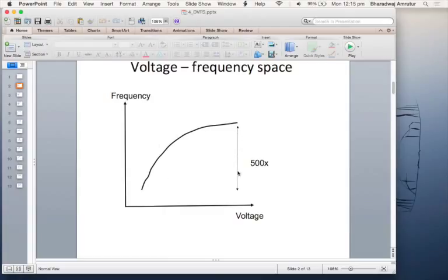But for now, let's worry about this range out here, where you drop your voltage from some max operating voltage to maybe about half of that. That is a reasonable range for your chips to run at, and you can change the voltage by about 400 to 500 millivolts, from the max voltage to the min voltage. That gives you a lot of voltage headroom to play around with to reduce your power as well as energy consumption.